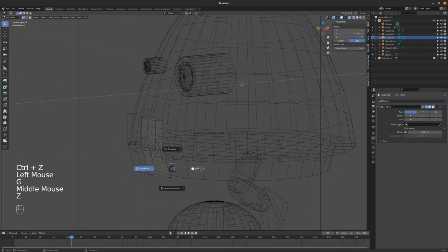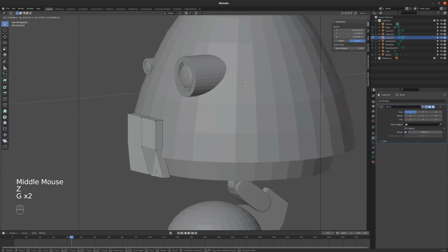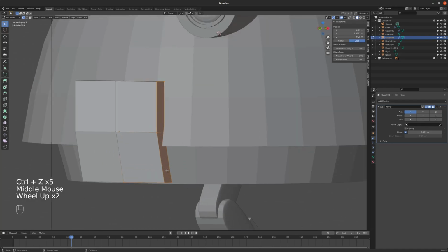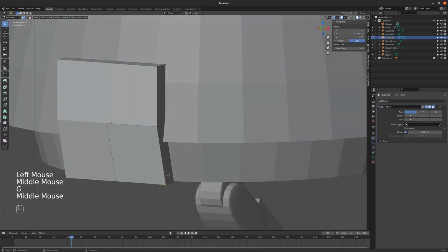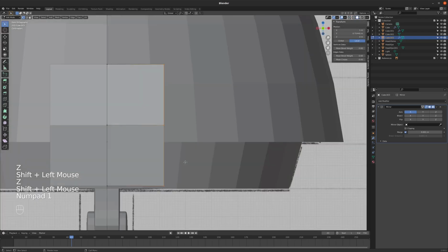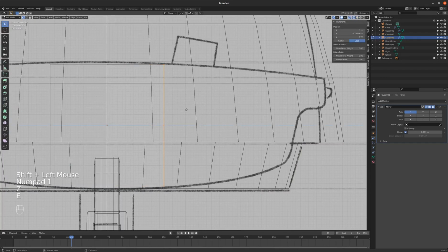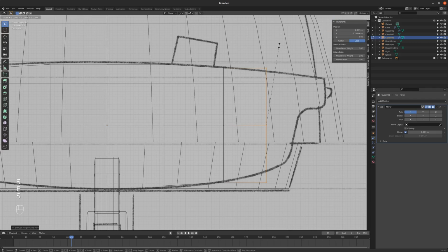Let's make sure we don't have any extra vertices here. Okay, and we do. So I need to do another level of undo. That's something to be careful of when you extrude. If you hit escape to cancel the extrude command, always make sure that you've hit undo until you don't have those extra vertices created by extrude stuck in there. Okay, extrude, scale in Z, extrude, scale in Z, GZ, extrude, scale in Z, GZ. So basically, I'm just going to create this one axis at a time.